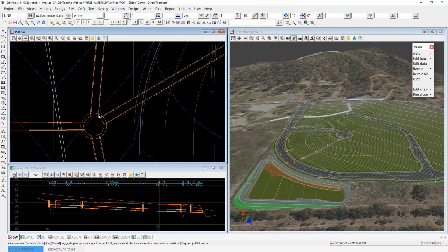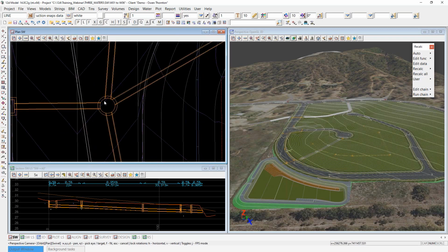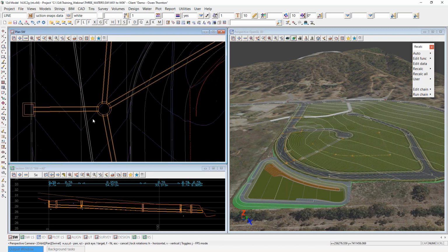those pipes look awfully close together. We could probably use a larger diameter manhole there to space those pipes out, but at the moment they're too close. Maybe another option is if we could shift these pipes so that they're connected to points further separated on the perimeter of this boundary, because at the moment they're too close to build, and you'd risk the structural integrity of that manhole if you tried to build something like that.